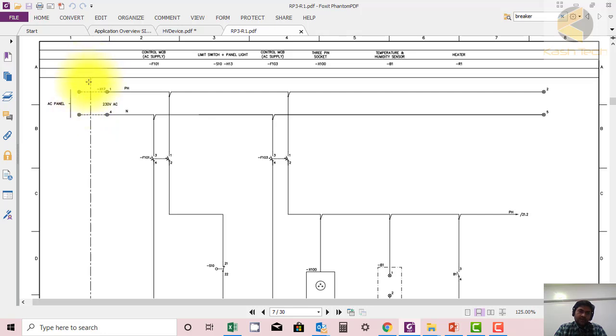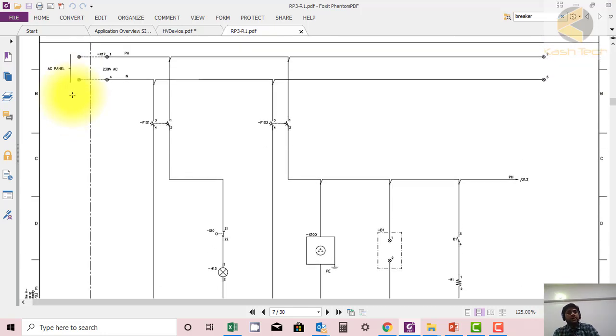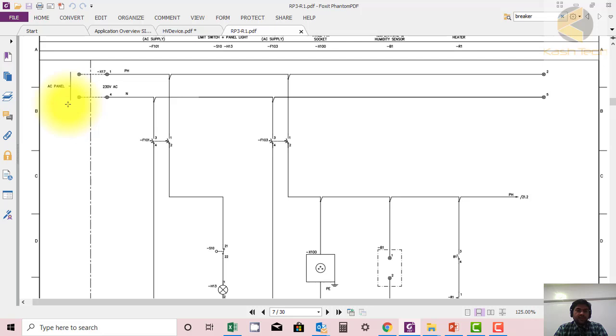The dash and single line show that this is not part of the panel that we are reviewing; it is an external source. Here at the external source no information, no panel number, is mentioned. So we can say the external references are missing in the drawing.